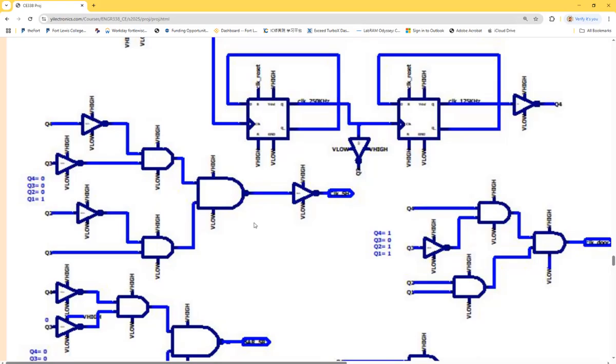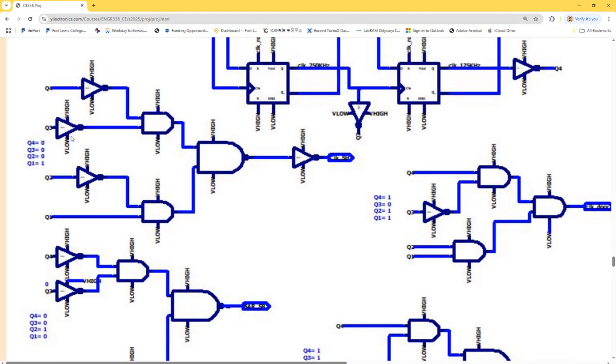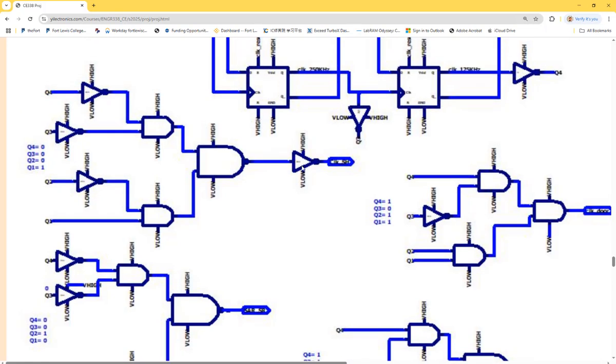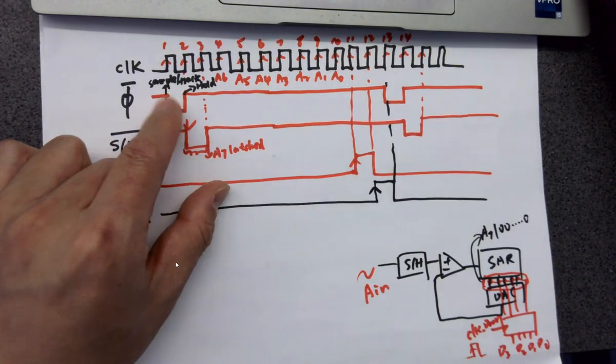Now let me take a look. So this is counting to 1. This is inverted twice. So I think this probably is wrong here. Yeah, I think I used the wrong circuit. This should be just a NAND gate because it's getting inverted. It shouldn't invert twice. Inverting twice is going to give you a rising edge, so it becomes a rising edge instead of a falling edge.